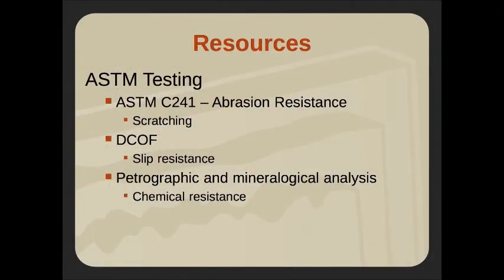It's important that we've done that homework. And then finally, we've got petrographic and mineralogical analysis, which we don't see very often. I've only utilized it once, and it was to solve a very particular problem, but that is available to us, where we can take that stone and slice it really thin and analyze it under a microscope and really come up with mineralogy of that material, and that helps us better understand whether it's going to be appropriate or not. Okay, so those are the industry standard organizations.